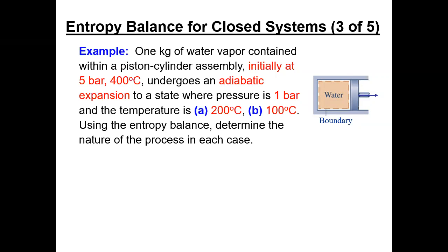Okay, well, as soon as you see that it's adiabatic, you know that the entropy can't go down. Because the only way entropy can go down for this is for heat to be transferred out of that mass, right? Because all you've got is heat transfer and production. Well, production is dissipative effects, friction, and at best it's 0 or it's positive.